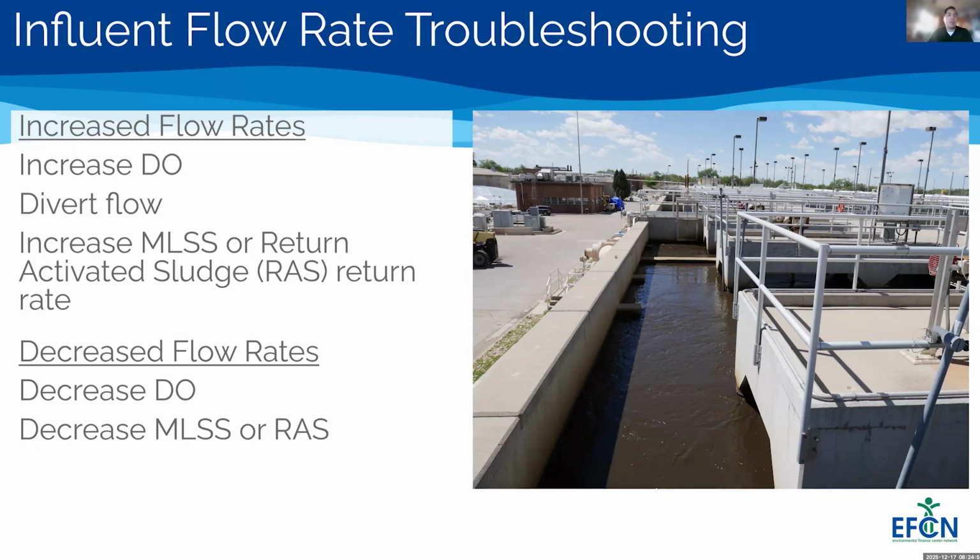We may also decrease the MLSS, or return activated sludge, so there's fewer microbes in the activated sludge process itself. And because of that, there's fewer organics that need to be treated as well, and that will help decrease things like the solids that we are discharging as well.